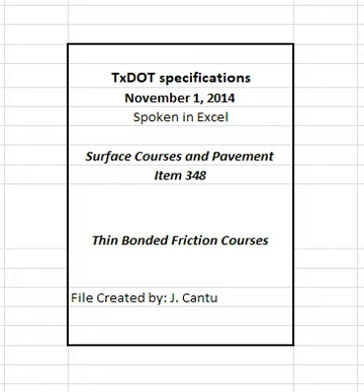Take corrective action any time the discharge temperature of the WMA exceeds the target discharge range. The engineer may suspend production operations if the contractor's corrective action is not successful at controlling the production temperature within the target discharge range. Note that when WMA is produced, it may be necessary to adjust burners to ensure complete combustion such that no burner fuel residue remains in the mixture. Control the mixing time and temperature so that substantially all moisture is removed from the mixture before discharging from the plant.